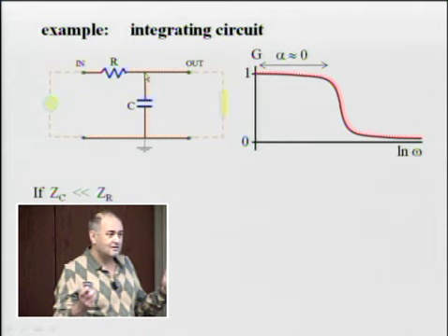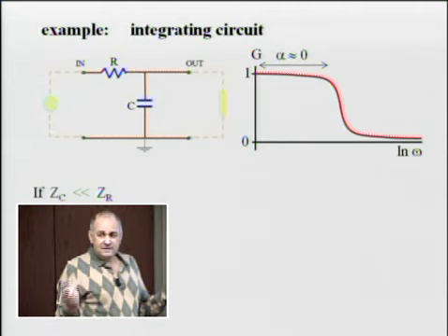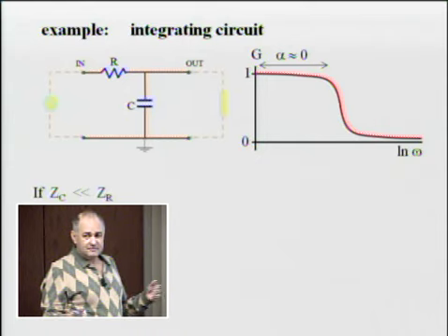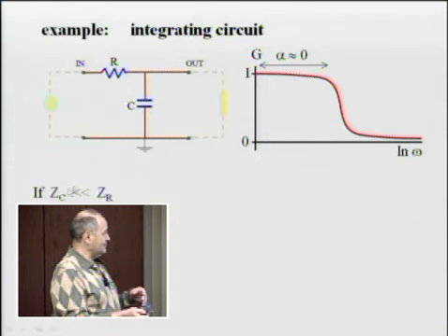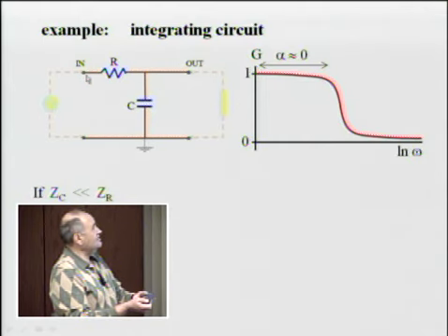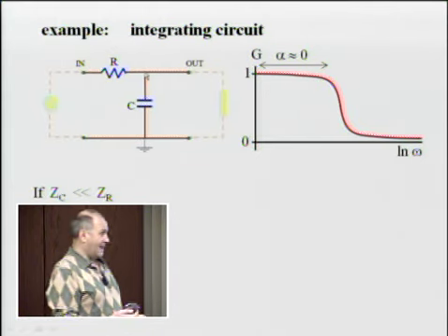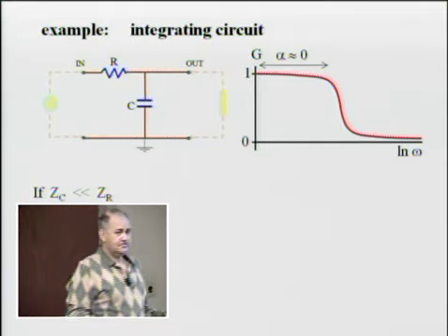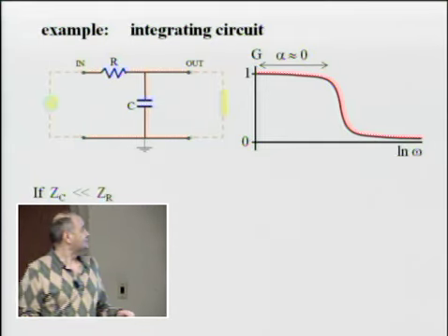Compare them. Their absolute values will be related by the same relationship. Therefore, the peak value of the voltage across the capacitor is going to be much smaller than the peak value of the voltage across the resistor. I can even think of the ratio as practically zero.